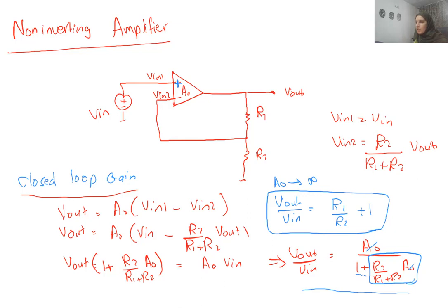And in circuit design, we typically like gains that depend on a ratio of resistors or a ratio of capacitors. Why? Because those are very useful to avoid variations when manufacturing the devices. Small variations in the width or length of the transistor can change the gm, and then they can change the gain. If you remember, the gains used to depend on the gm, while now we have a gain dependent on the ratio of those components.